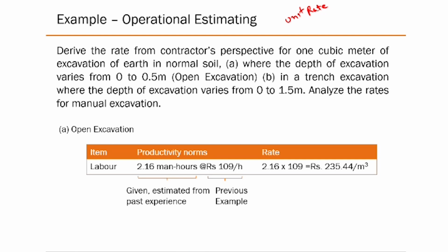Now the challenge here is that there is no fixed definition of what a unit is. It depends on the activity. For example, for concreting work, we saw the unit as cubic meters of concreting work. Just for material, cement bags, we calculated in terms of kgs. For the steel, we calculated in terms of again tons or kgs, right? Earthwork, you will measure perhaps in cubic meters. If you are to do work on plastering, you will measure in terms of square meters. So there is no one standard unit. The unit keeps on changing depending upon your activity, but that's how it is, right?